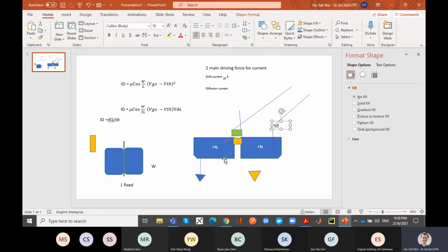Why? Because there are certain effects at high field. Number one, you actually get more scattering. The electrons will start whacking each other and the lattice more, so they get slowed down. And number two, there's a mobility effect as well. So there's an effect called velocity saturation, which is sort of like saying that this transistor is a little bit weaker.